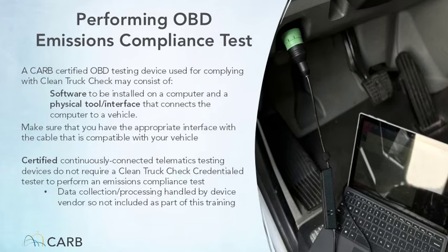To perform the OBD emissions compliance test, the appropriate testing device interface adapter that attaches to the DLC is required. Testing devices used to complete the OBD emissions compliance test may vary, but in general, will likely operate similarly to the one shown here. Refer to the owner's manual of your specific testing device for installation and operating instructions.